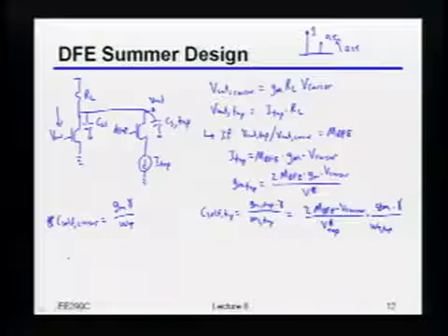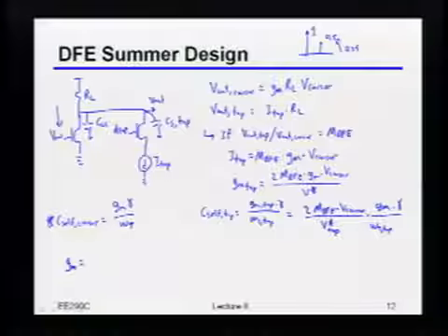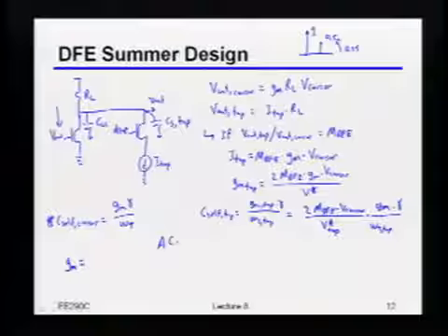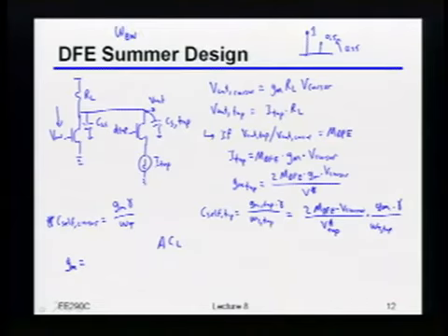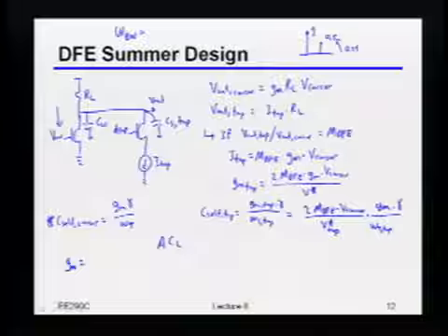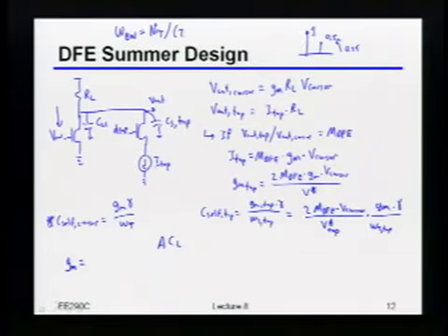So just like I did before, I can rearrange everything and do the subtractions and all that. The details there are actually not that difficult. If you do that, what you'll end up with is something like the following. The GM that you need, as before, on the numerator, you need some gain, you have some load capacitance, those are just going to be proportional. The only thing I'm going to do is remind you that the bandwidth you need from the summer node is again going to be n tau divided by the bit time minus the digital delay. I'm just going to write everything in terms of that so that we can see directly how those things come into the picture.